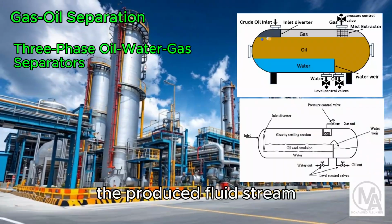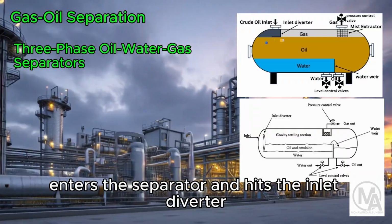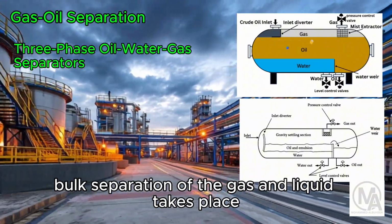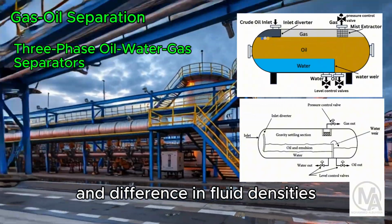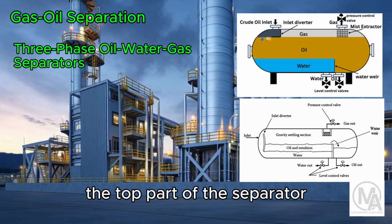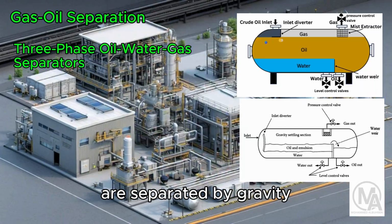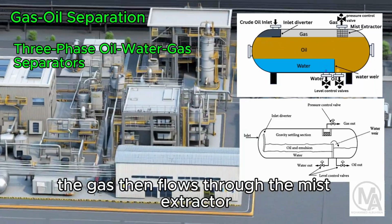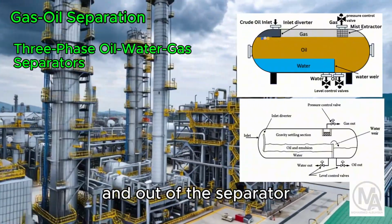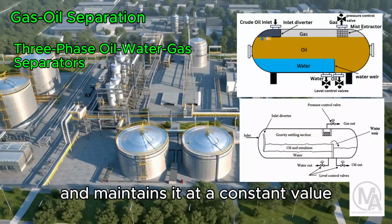The produced fluid stream coming either directly from the producing wells or from a free water knockout vessel enters the separator and hits the inlet diverter, where the initial bulk separation of the gas and liquid takes place due to the change in momentum and difference in fluid densities. The gas flows horizontally through the gravity settling section, the top part of the separator, where the entrained liquid droplets, down to a certain minimum size, are separated by gravity. The gas then flows through the mist extractor, where smaller entrained liquid droplets are separated, and out of the separator through the pressure control valve, which controls the operating pressure of the separator and maintains it at a constant value.